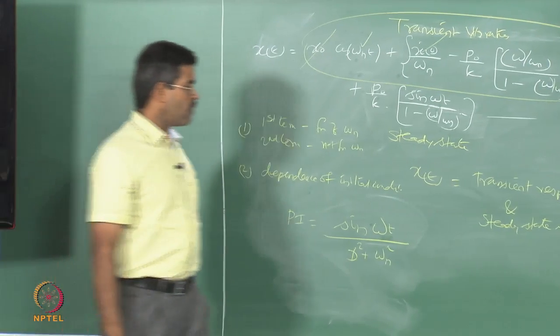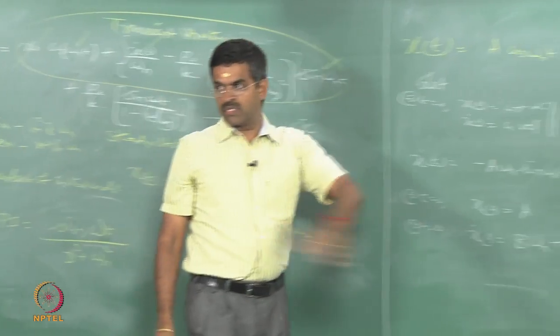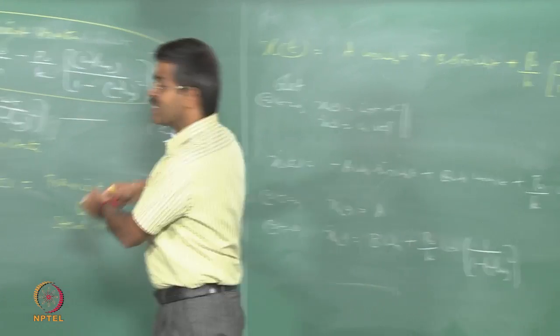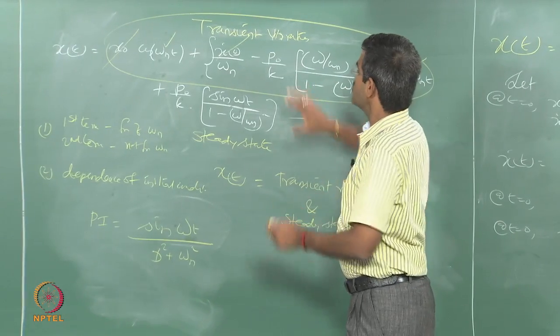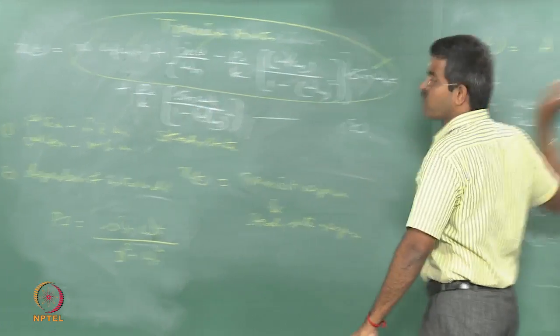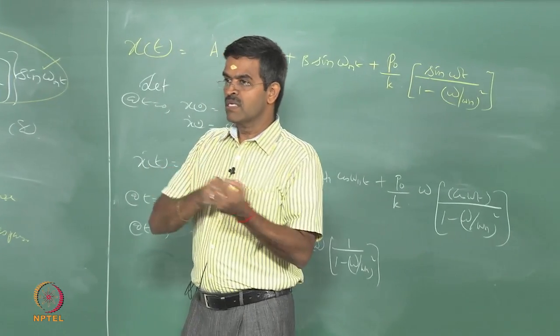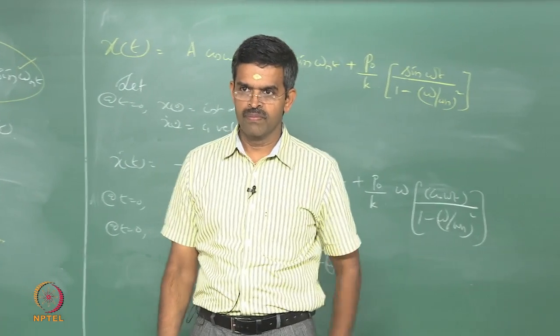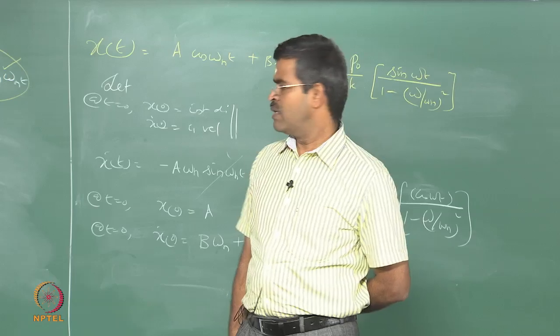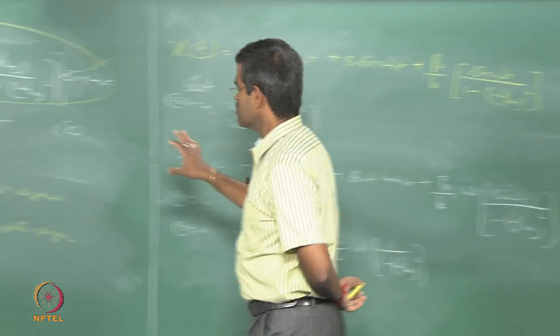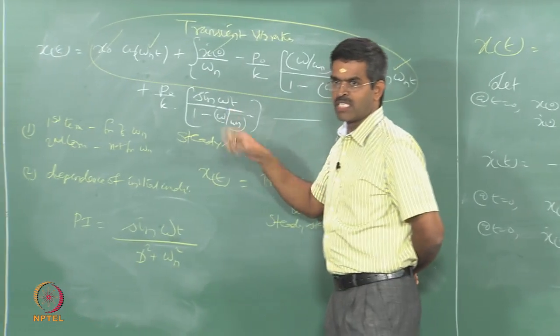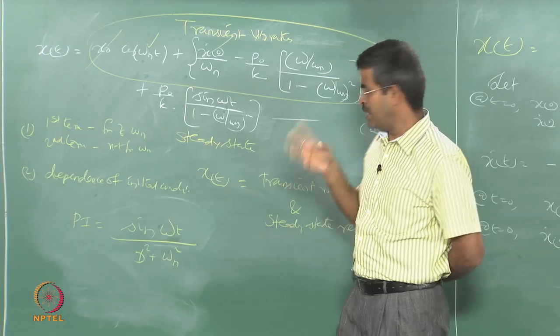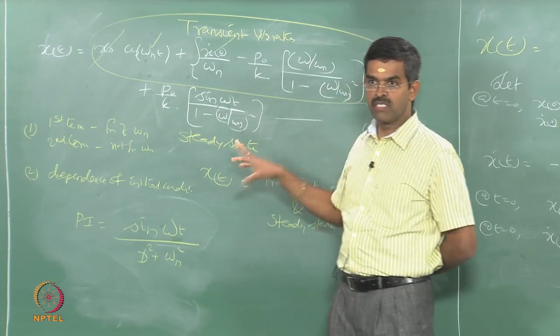Therefore, to get back to the same equation where resonance will set in, I look at this whole concept in a slightly different form called dynamic amplification factor. In structural dynamics, the whole concept of resonating frequency is expressed through beta, where beta is the ratio of the frequencies.